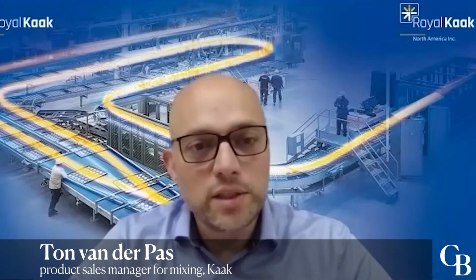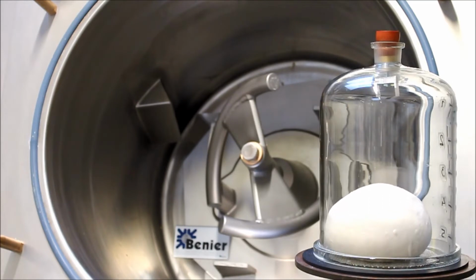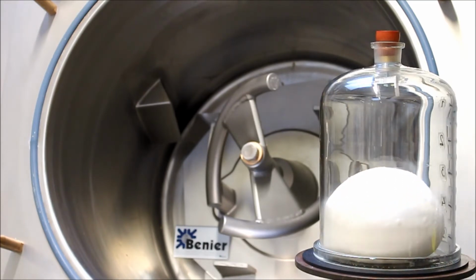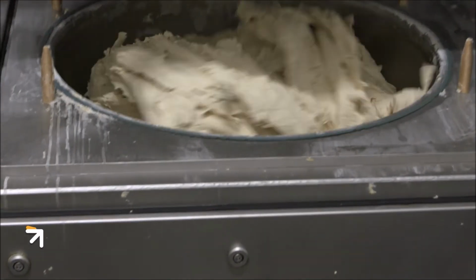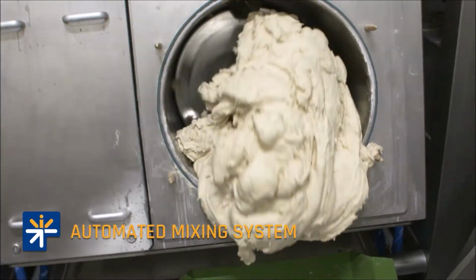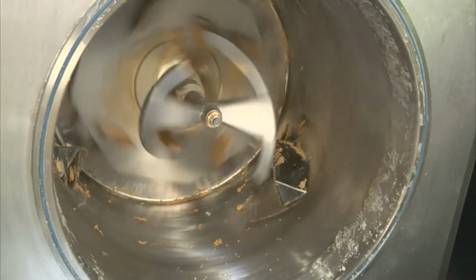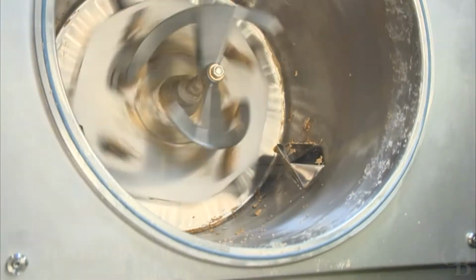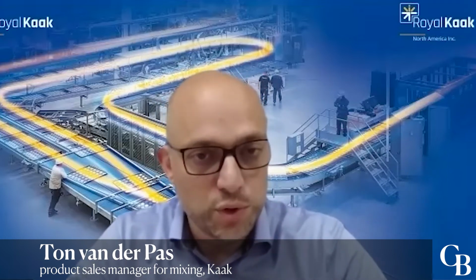With vacuum mixing, while mixing, the gas trapped in the dough will expand, and during the mixing cycle, that gas bubble, which starts to grow, will be divided into smaller gas bubbles. And just before the mixing stage is done, you release your vacuum so that the smaller air bubbles, which are distributed through the dough, become even smaller. So vacuum mixing creates a fine distribution of finer cells. At the end, you have a product with a fine cell structure.